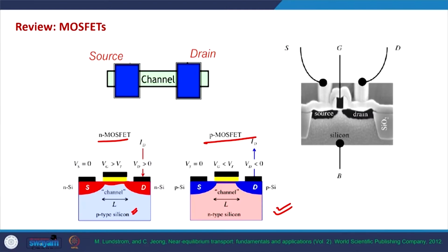And by inversion layer we mean that originally this body or the substrate is P-type silicon, but by the electric field due to the gate voltage, now the electron concentration very close to the interface between the oxide and the body is so high that it behaves like an N-type material, and that is why there is a conduction pathway from the source side to the drain side, and this is at the heart of the functioning of a MOSFET. So please keep this basic thing in mind.